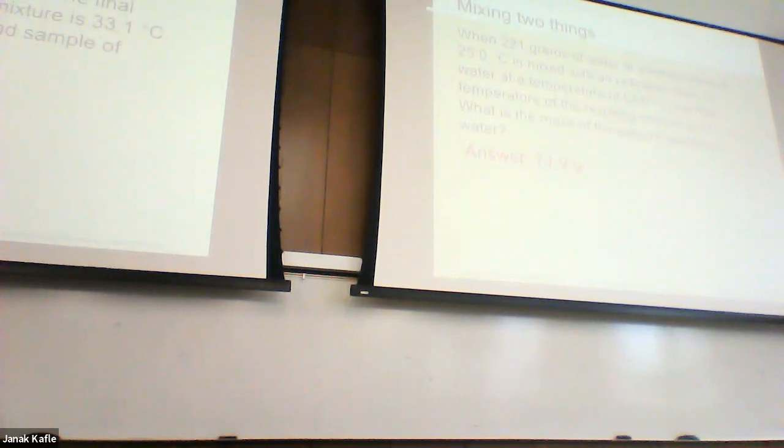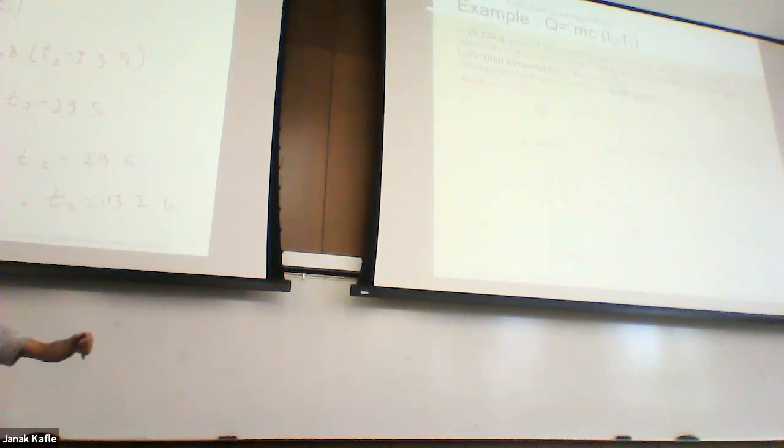Same thing here, but calculating temperature, so we need to be careful. I will talk a little bit here. Previously, when I was calculating the mass and specific capacity, I told you if you get a negative number, just get rid of it and write the answer. But in the case of temperature, we cannot do that, because if we disregard the sign, rather than coming out too high, sometimes it goes too low. So we need to take care of the negative sign here.